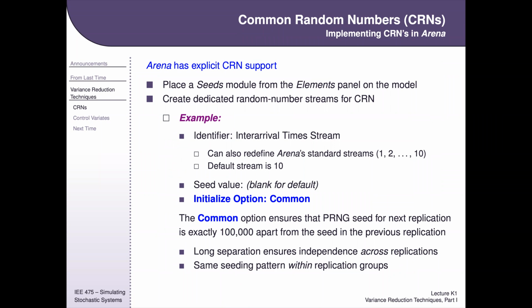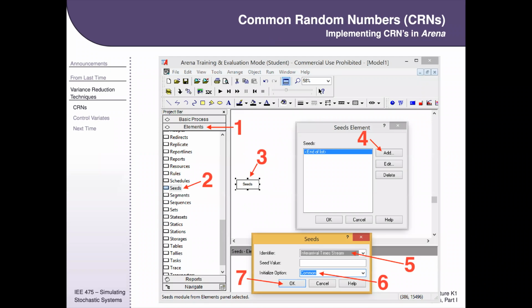So if you do a 10 there, then it'll automatically do it for all of yours. Otherwise, there is a second argument whenever you run a random number generator, like Expo. If you do Expo 5, that'll give you an exponentially distributed value with an average of 5. If you do Expo 5 comma something, whatever that something is after it is this identifier here.